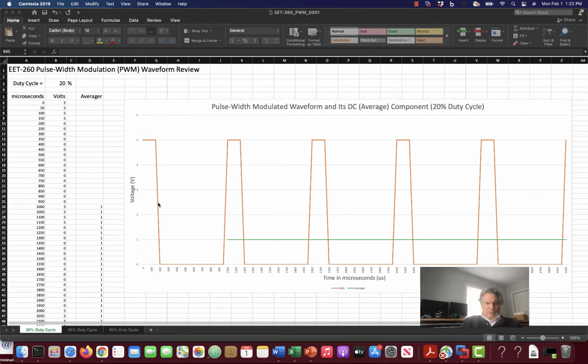Now, if we drive this into something slow, like a DC motor, what will happen is the motor will just kind of laugh at this pulsing thing and say, I'm just sort of going to integrate, if you will, or kind of take the average feel of these punches, and they feel like I'm being hit with something that's about 1/5 the full voltage, because it's the full voltage on for 1/5 of the time.